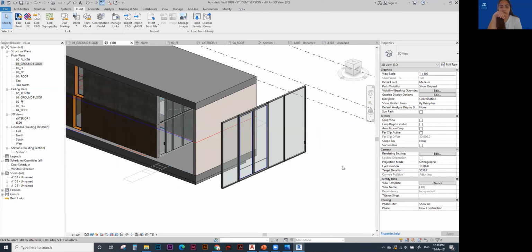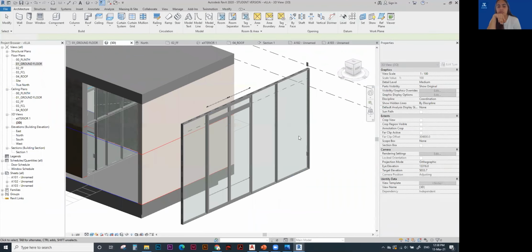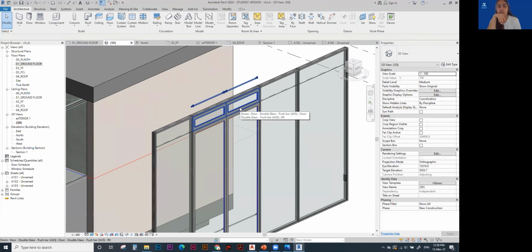And if I change the height of this, the whole thing changes. I want this to go until, say, FCL, the whole thing changes. And if you want to add another mullion, that's another mullion, say at 600 from that level. I'm going to make this 600 mm, and then it creates that thing to be 600.